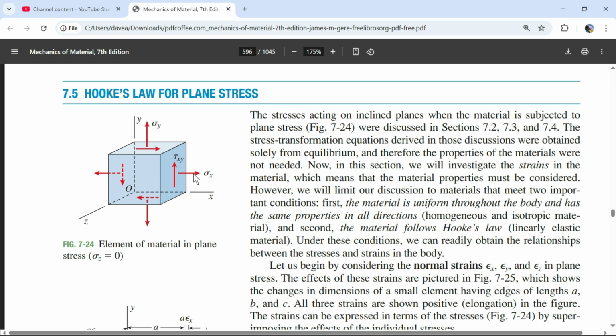So biaxial stress, two tensions. With a 0 rotation, you're just going to have normal stress. But when we rotate this, then you get shear stress, and that's going to become maximum at 45. Okay, hell yeah. So that's kind of what these sections were all about. Still, these three numbers are the only numbers. We don't have any shear in this. On this face, you can only have a normal direction. You can't have a positive arrow and a negative arrow at the same time.